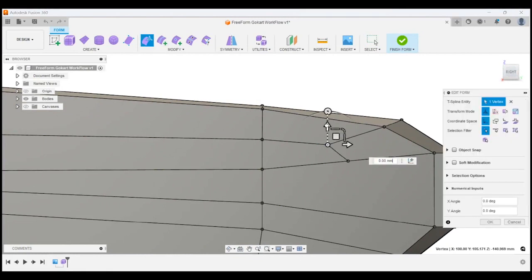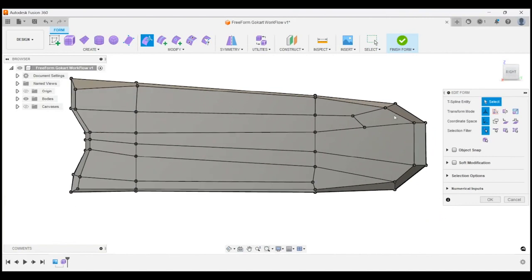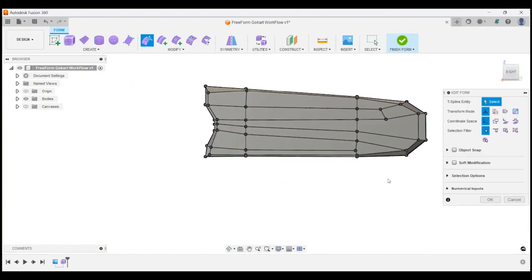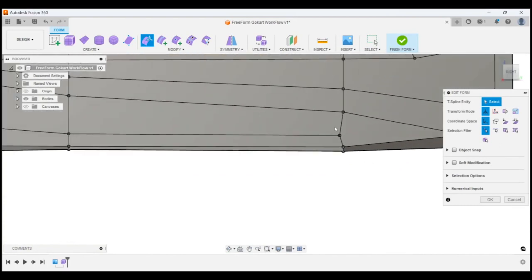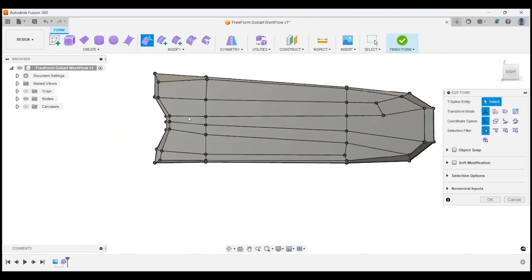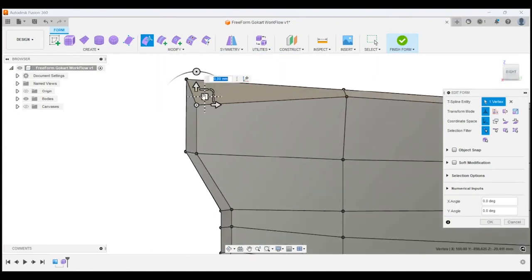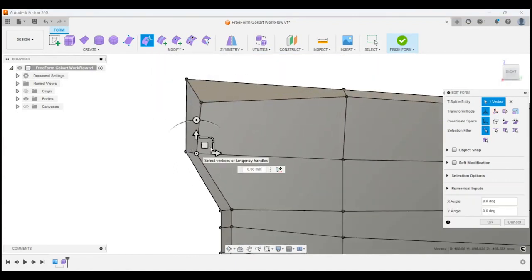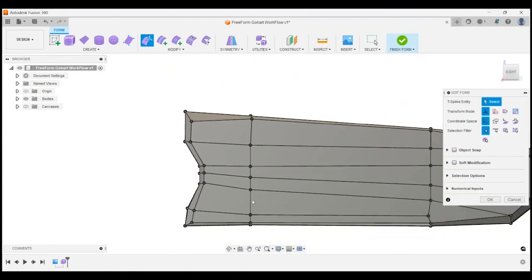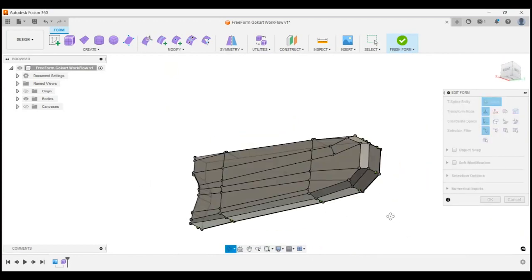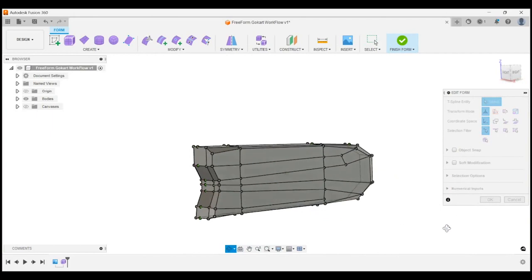I would definitely like that a bit smoother, but you know, realistically in the competition you're not going to have time to address every little vertex and make sure it's nice and consistent, but definitely while we're practicing and while you're learning how to do T-points, it's a very good practice to get into, and in the competition then you can decide whether it's necessary. But when we're practicing, it's always a good idea to keep everything consistent. Nice parallel lines where we can. So we'll leave that for now, and we'll go on and make this a solid body.